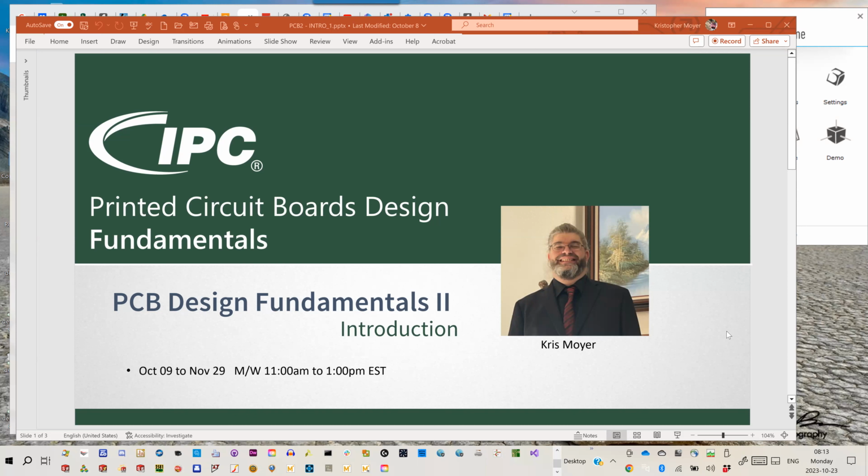Now, should you extend it over the whole board? All I usually do, if I'm going to do anything with that, is right click and wrap an orthogonal or even a non-orthogonal room, so it's a weird shape rather than a full rectangle. But again, once I've done that, I just make the rooms invisible when I'm ready to do my route.